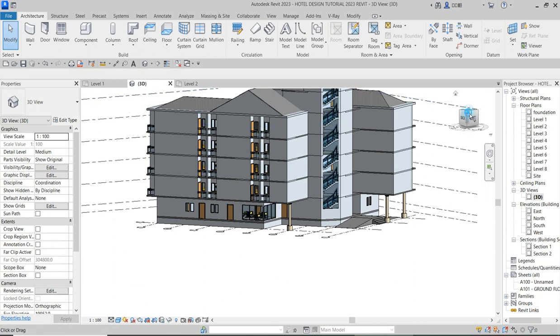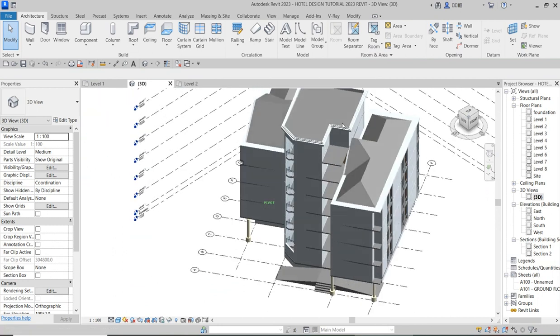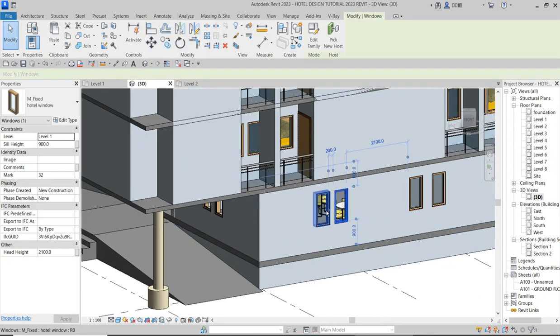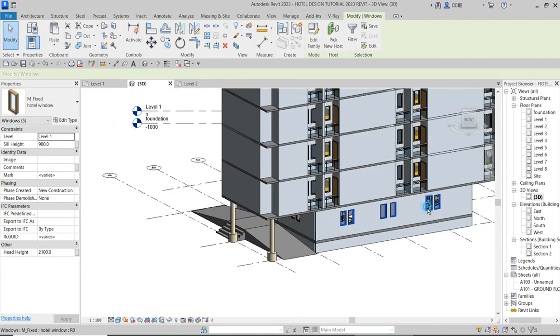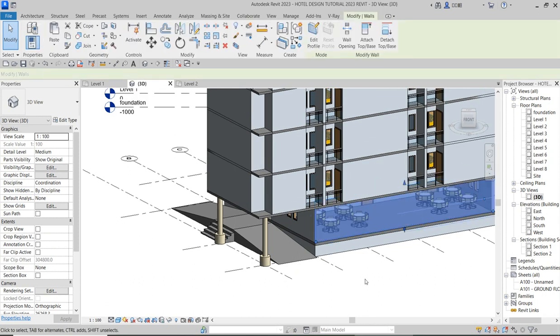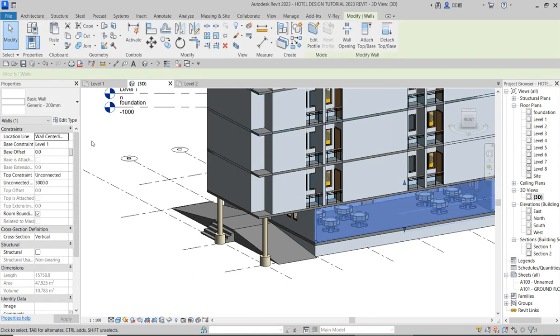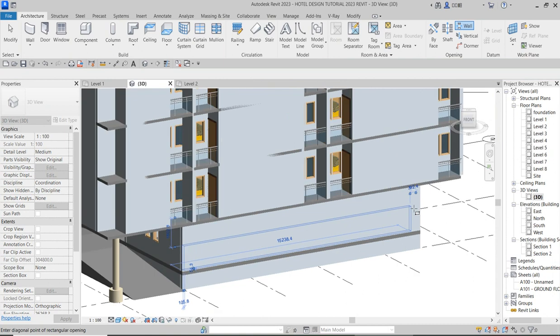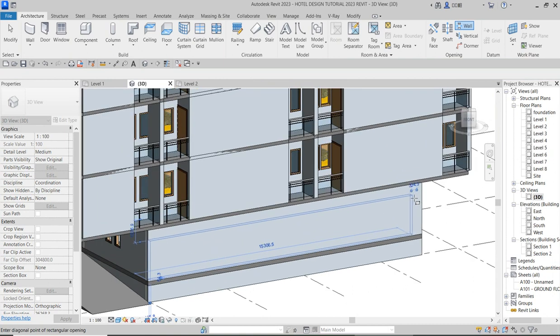Then let us go and do the same thing at the hall level. At this hall level 2, I'm deleting this wall. So actually everything here will be something I'm going to work on like that. So I just want to create a split wall. Click on this wall and you say split. So you start from the beginning and go to almost the end.